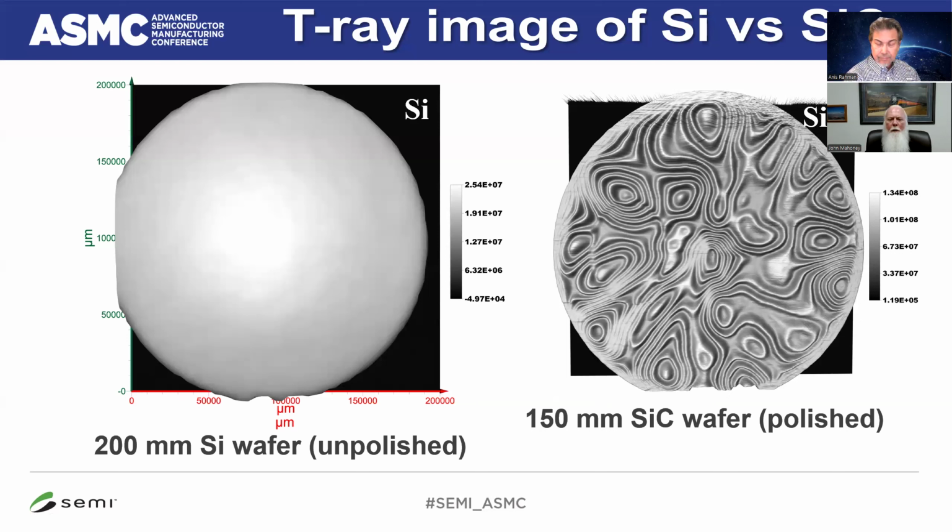And these silicon carbide wafers, the polytype on these is 4H, mostly 4H. Some of the variations we're seeing could perhaps be polytype variations. Again, I am not sure, but I don't suspect a polytype variation, because industry has checked on that more than anything else. Since they see the same polytype, they think it is something else. They do not suspect the growth process.